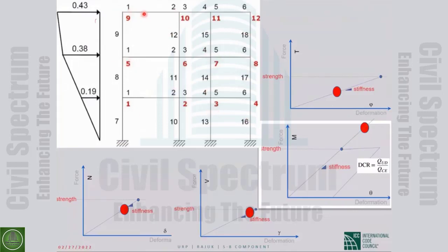Put the gravity load, and from the response spectrum calculate the period of the building, we get Sa times the weight of the building, and then modify that base shear to have the same displacement as the real building, so multiply by C1, C2, and Cm, and distribute the load here, and look at the elements.